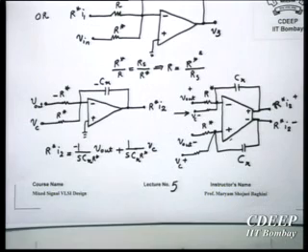So it has several advantages. First of all, circuit is not sensitive to common mode noise, right? The second advantage is, what is the second advantage of a differential architecture? Any guess? Having more PSRR, right?